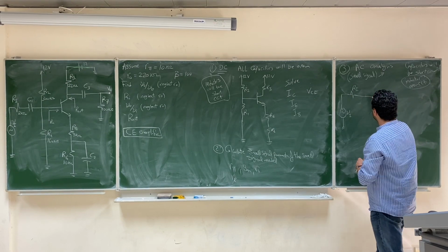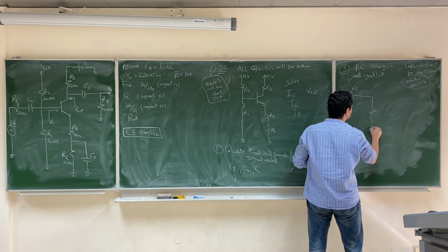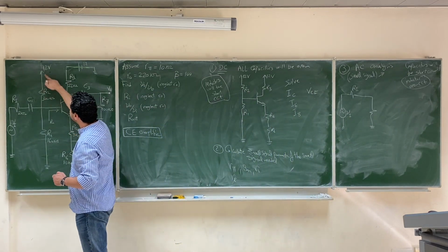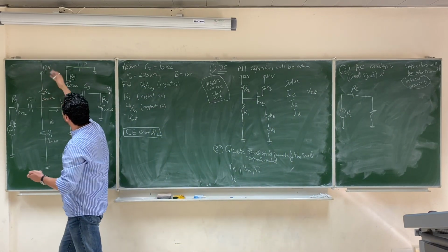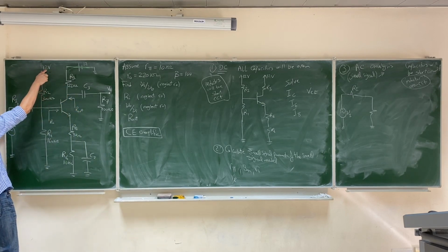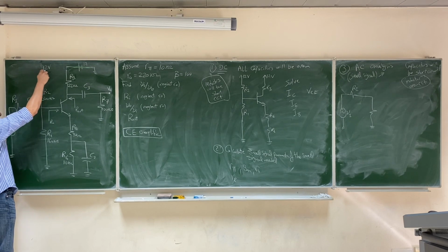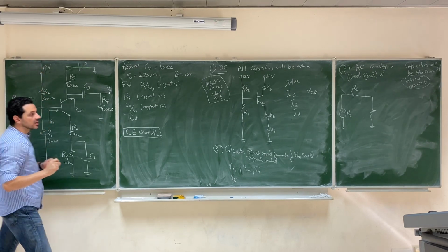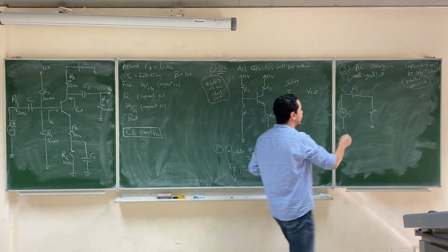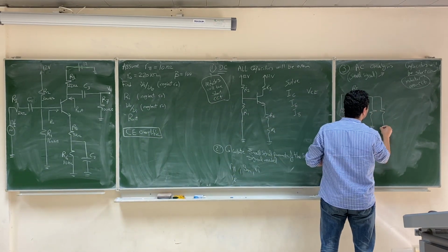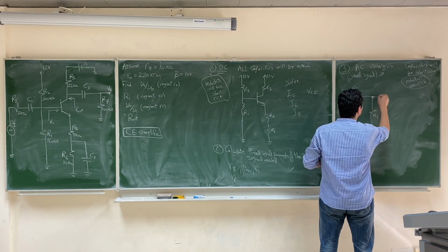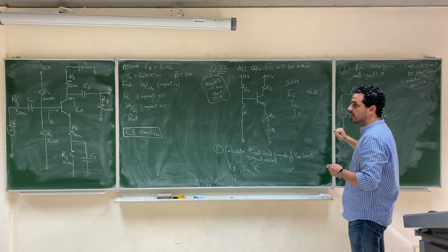In addition to that, this resistance R1 is connected to ground, and then this resistance will also be connected to ground, because we said when we deactivate this DC source, then implicitly you are going to connect this to ground, right? So R2 is connected between this point and the ground. So you can plot it like this. R2 between this point and the ground. So you can plot it down, okay?